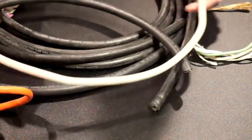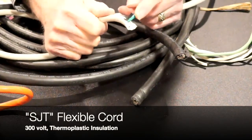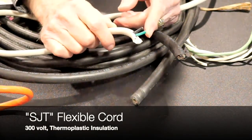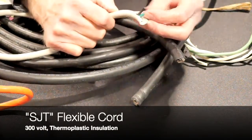Here's a typical cord. It is SJT. So the SJ tells me that the insulation is rated for 300 volts, and the T tells me it's a thermoplastic insulation. So this is a thermoplastic just like we'd find on our typical building wire then.